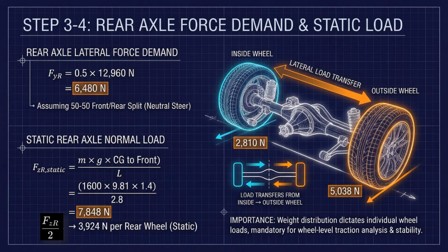Now we estimate how much sideways force the rear axle must carry. Assuming the car shares cornering evenly between front and rear, the rear axle takes half of the total lateral force. So the rear lateral force, FYR, equals 6,480 newtons.